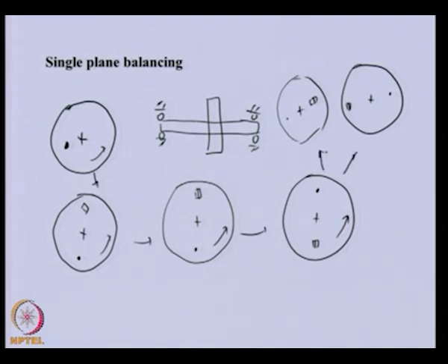So, like this we are able to do the static balancing. Most rotors in which most of the mass is in one plane can be balanced using this procedure, like the propeller in an aircraft, in which most of the mass is situated in a single plane.